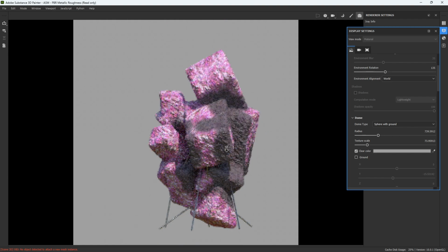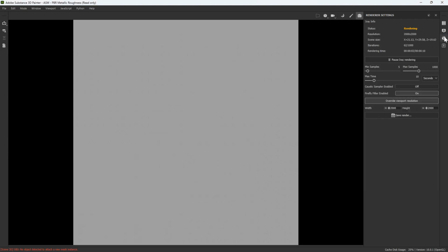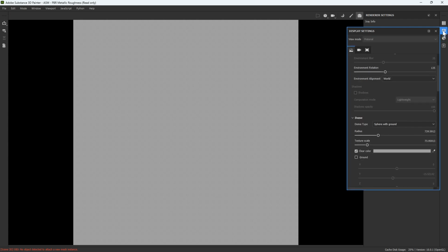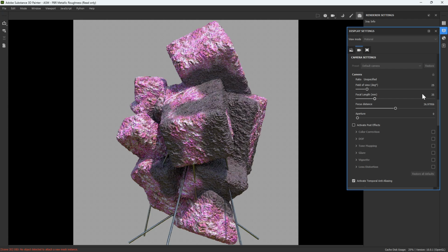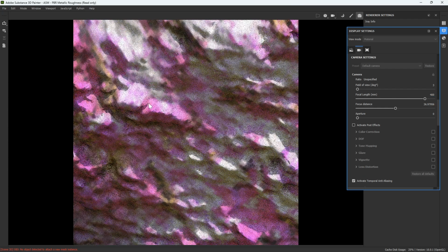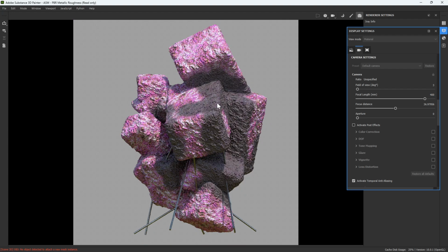Okay, cool. Now I should be able to... When this happens, what I'm experiencing is the geometry is disappearing. I can come back to my camera and take it back to say a different lens length, like 25, hit F, focus in, and then if I want to go back to my flatter lens length, like 400 or 500, I can do this and then hit F again, and that should fix the problem.